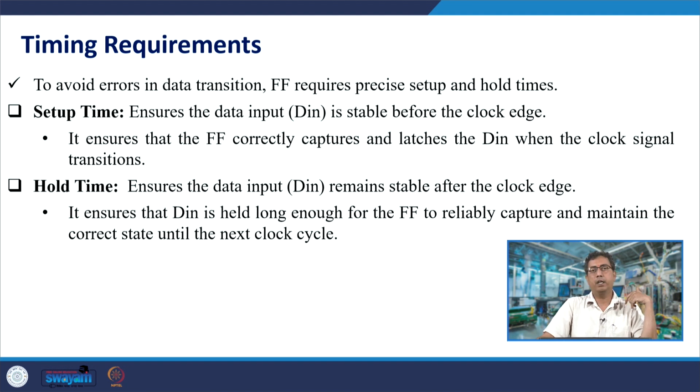So, for this negative edge triggered clock, sufficiently before the clock turns 0, and the input data D in should not change till a while after the clock turns 0. That time is hold time. So, these are setup and hold times, and these should not be violated. If these are violated, it may result in the metastable condition that we had discussed just now.